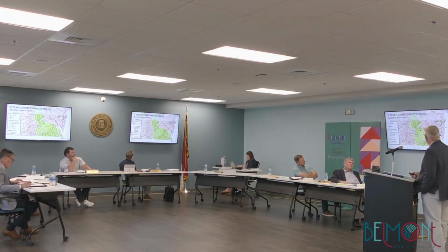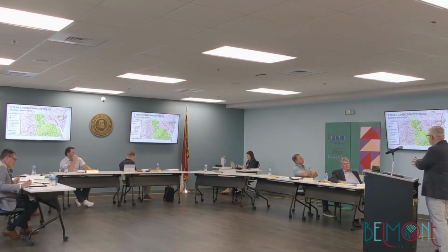Now I'll come down to Belmont, kind of what I'm calling the wastewater treatment plant area. Same kind of thing, you can see that same pattern forming again, right here from where it says City of Belmont wastewater going kind of northwest again. That is additional lines in that area. They are surcharged underneath that 2-year storm event. And again, we've actually witnessed this physically during those events on the ground, but we're also seeing those same results inside the model, which gives us a lot of confidence in the data that we're getting.